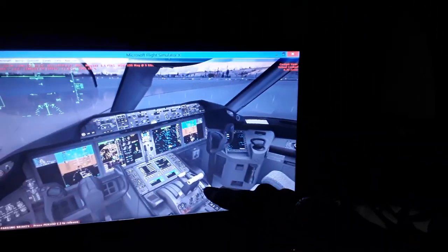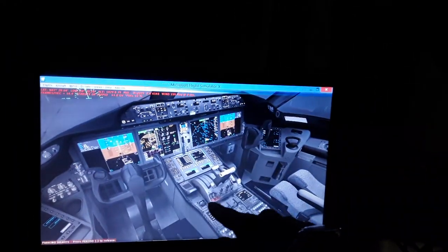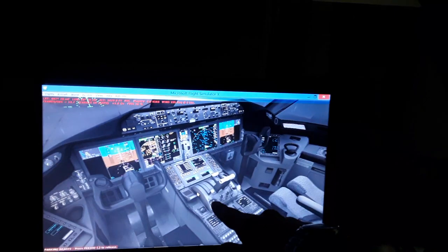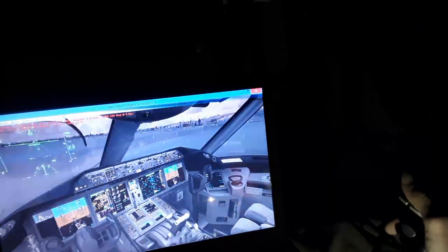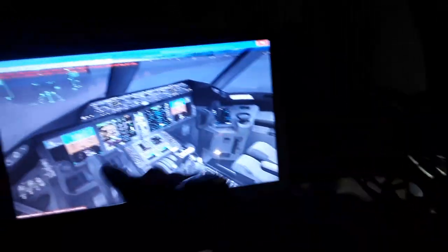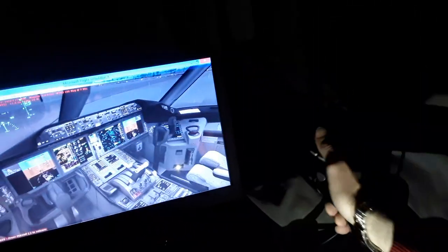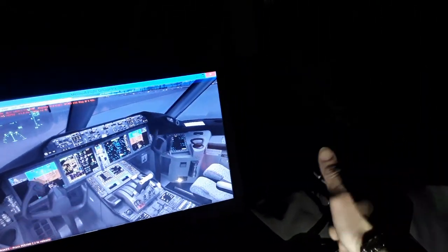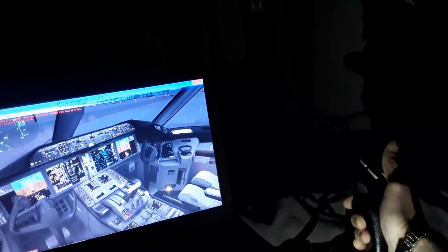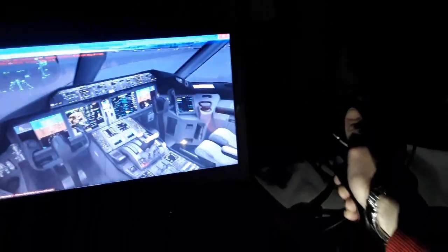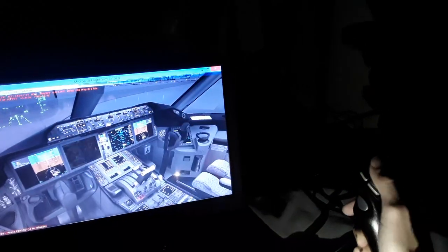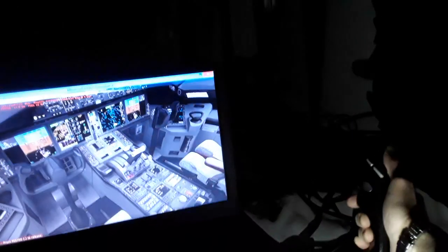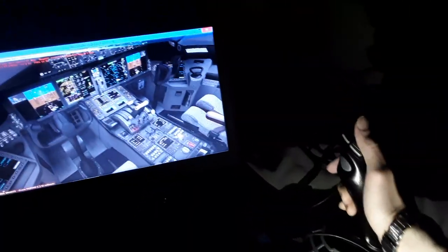We have the flaps and the slats. I will show you the speed brakes later. Horizontal trim stabilizer also here and here and here, and horizontal auto trim cutout switch. You can see the captain and the first officer are interconnected to move together in flight, unless you have a failure. They're not like in the Airbus. You have the side stick priority. You can take the other side using the side stick deflection.